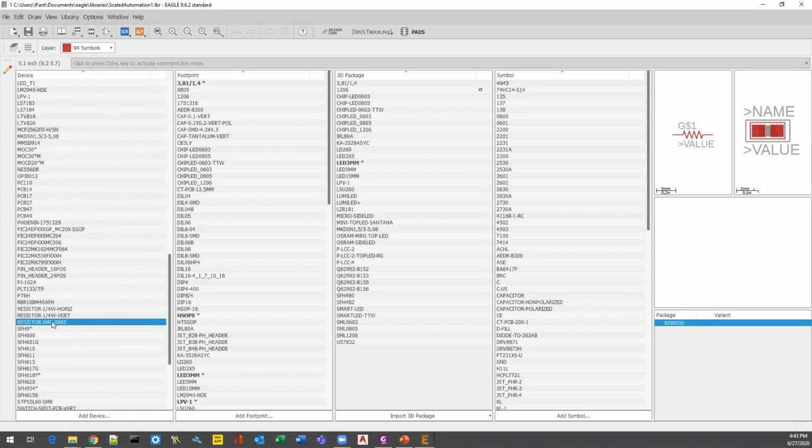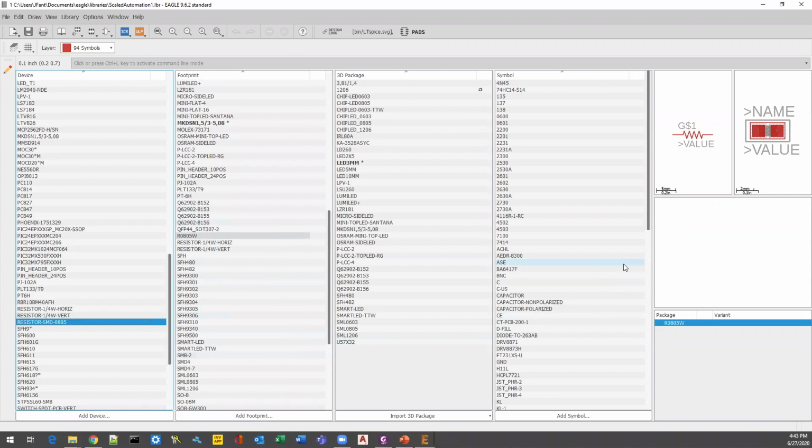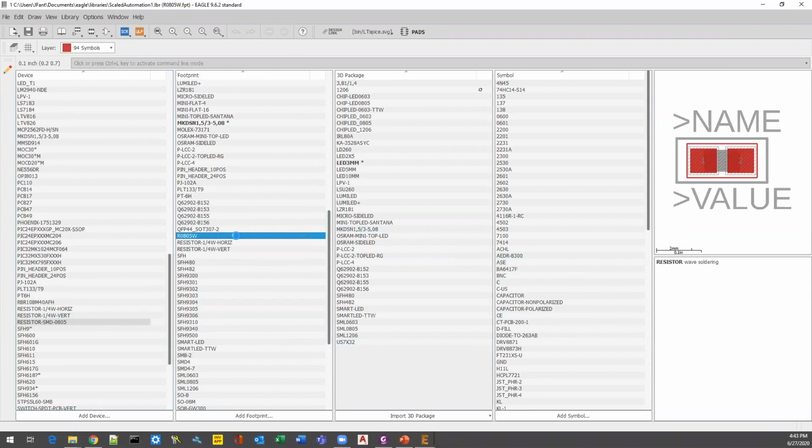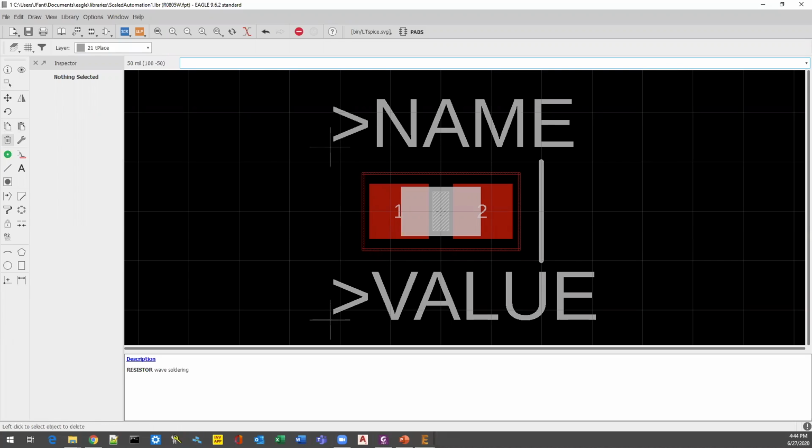resistor-SMD-0805. But what I want to modify is the footprint. So what I want to do is find its footprint. And there it is. It's highlighted for me. I'm going to double click on it to open it. And there it is. Notice in this one, the outline has already been added. So the problem we have is that the board has not been updated. So this one has got the outline on it. I'll show you real quick what we would do if that outline wasn't there, and I'm going to just take those outlines off.